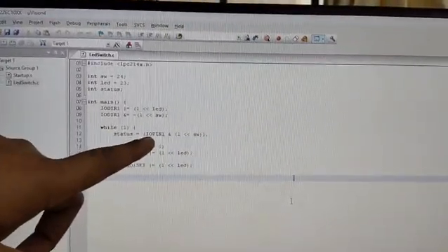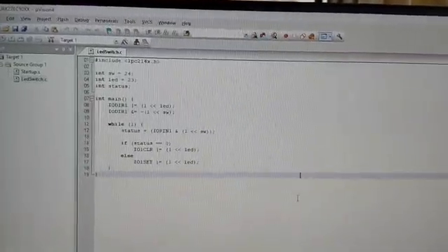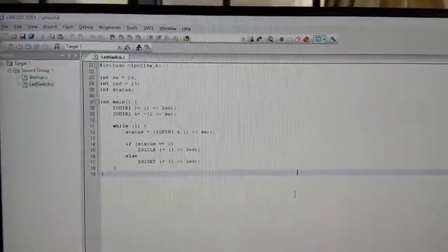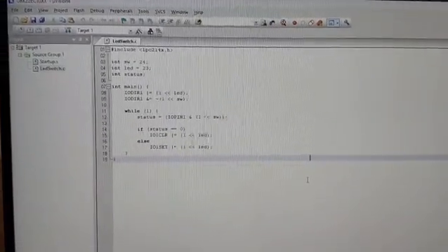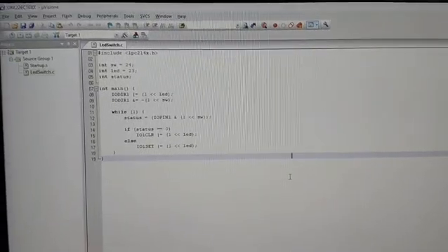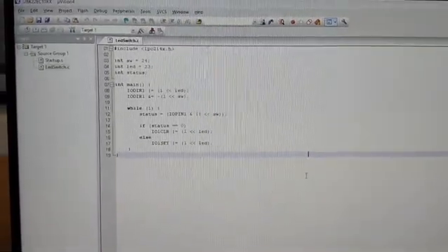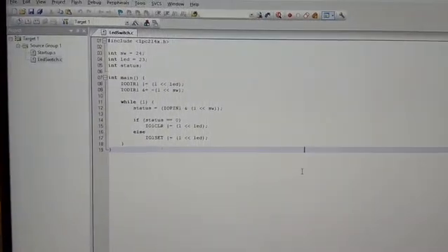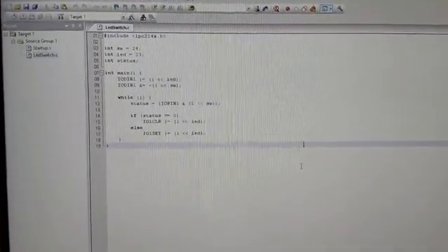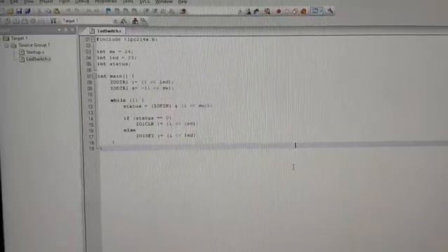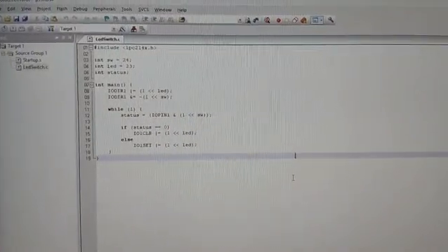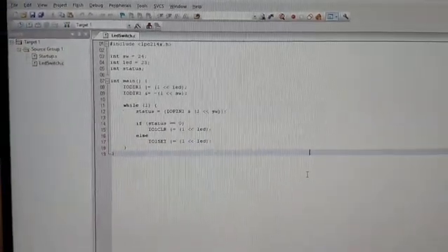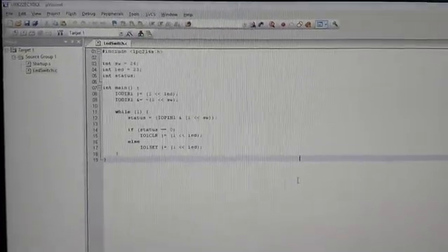What the IO pin does is it checks whether the switch is on or off. So it is used to check it. If the switch is on, the status would be true, so the AND operator is used. Only when both the conditions are true, it gets turned on. Based upon that, we are turning the LED on or off. So this is one switch and one LED interfacing.